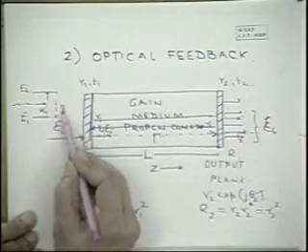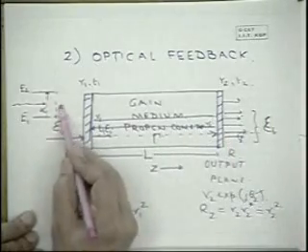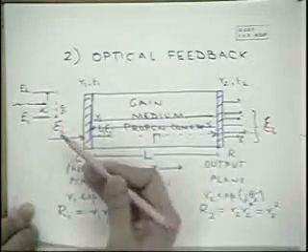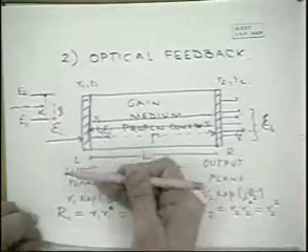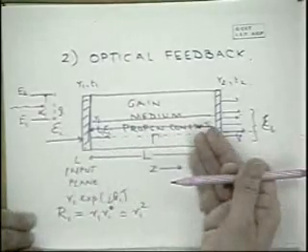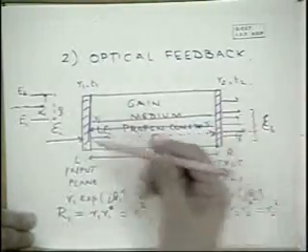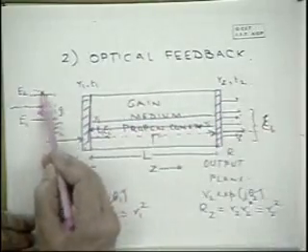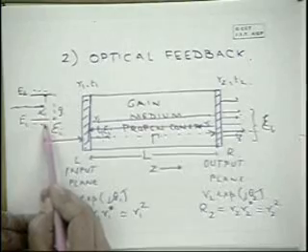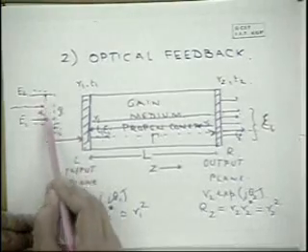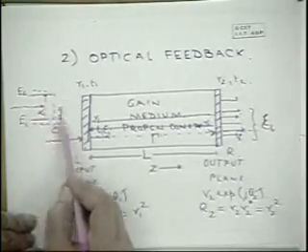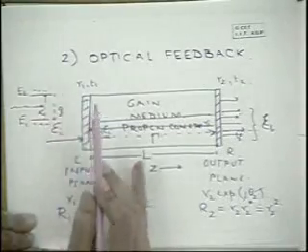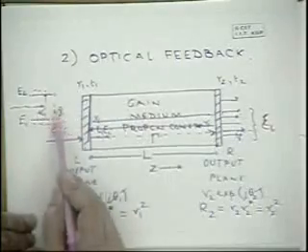And how does gain increase? Obviously, if you pump, for example if you increase the current, then the excess carriers delta N, delta P increase. Delta N, delta P increasing means there is more recombination. If there are more electrons in the upper state and more holes in the bottom state with increasing current, then obviously this will increase and G will increase. So there will be some threshold current beyond which it will start lasing.